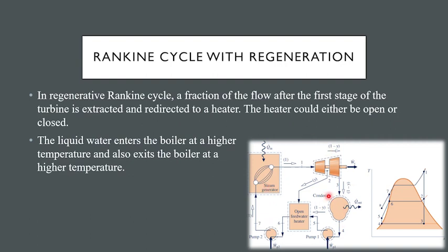If we map this process into a temperature entropy diagram, you would see that typically stream 1 is a superheated vapor. Upon passing the turbine, it is converted to a saturated mixture, that is stream 3. However, stream 2, which is still a superheated vapor, is subtracted from stream 1 and is sent straight to stream number 6. From stream 2 to stream 6, you would see that it is being condensed because from a higher temperature, because it is superheated, it is brought down to its saturation temperature, and then from a saturated vapor here, it is converted to a saturated liquid. So stream 6 is a saturated liquid, meaning it is at its boiling point.